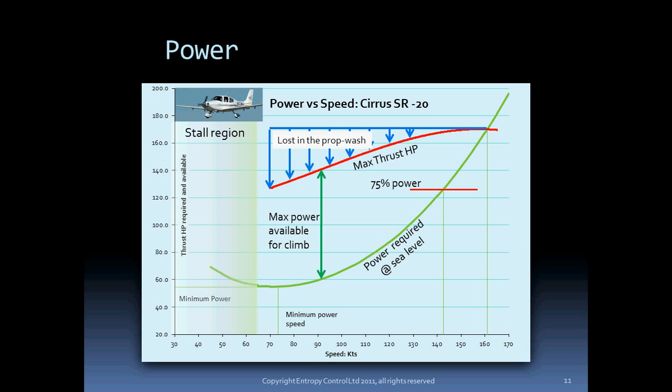If you find that you're going to be a bit short, accelerating to 96 knots gives you a better glide angle, particularly into the wind. If you're already at your best glide and you're coming short, then you really are out of options.